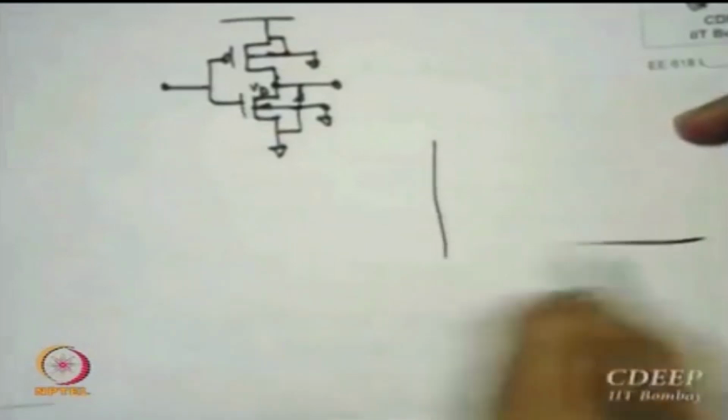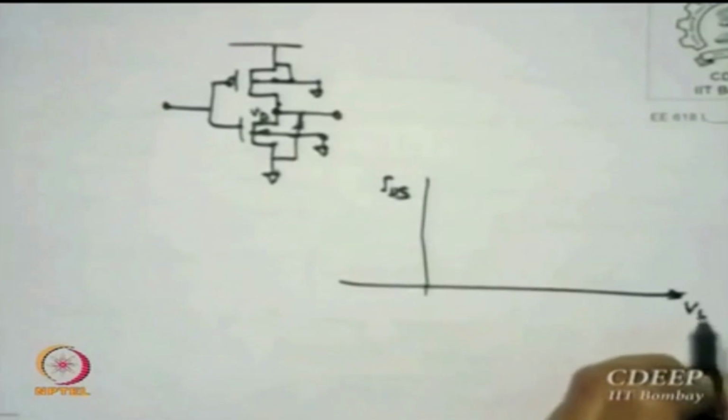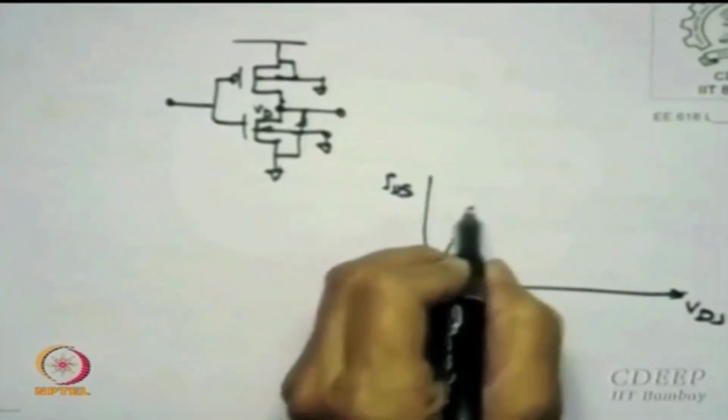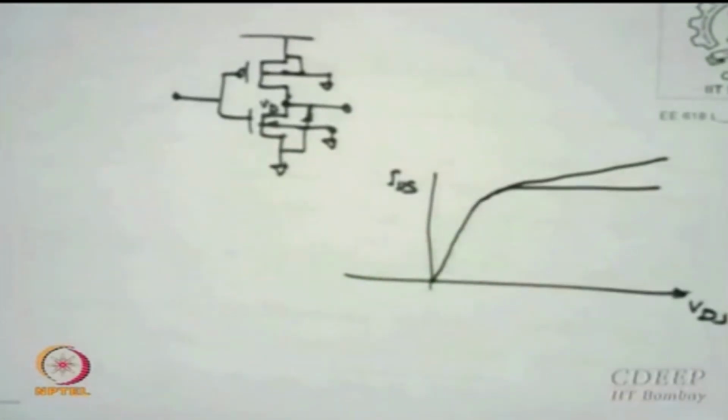that is why in our transistor characteristics we did observe in the output characteristics, IDS versus VDS for any VGS, initially it is linear, then we expected theoretically something like this, but what we got is this, because as VDS increases the effective channel length reduces. But that also influences the lambda itself, and that is the interesting part. This is one effect which is obvious, and it is called channel length modulation. Why is it modulation? Because the channel length gets modulated, changed by VDS.